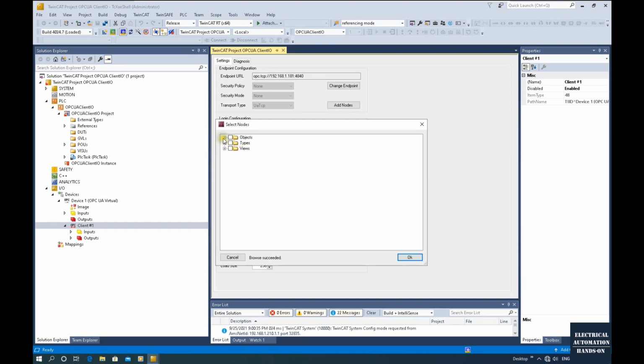From these objects here, we can see this is the OPC UA server S7-1200 I set up, especially this server interface. If you recall, the server interface underscore S7-1200 N1, that's the interface we set up. Under this interface folder, we can see the data 1 to data 10, and the sine X and sine Y, also the test data A, test data 2, and some miscellaneous data here. Then we can click the data we are going to browse from the client side.